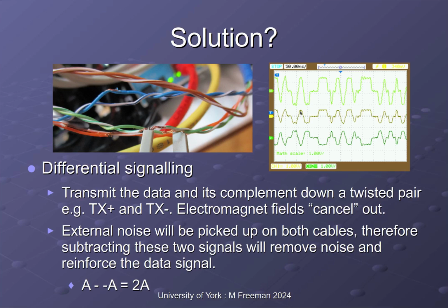So you can see as our data bit goes high on one wire, it goes low on the other wire. So we get positive voltage minus a minus voltage, which doubles our signal, gives us a nice larger signal, which helps us when we're thresholding: is it a 0 or is it a 1? Because it separates the logical levels, they're less susceptible to small noise variations, which will occur in any digital system. So yes, this is perfectly acceptable in terms of digital signals.